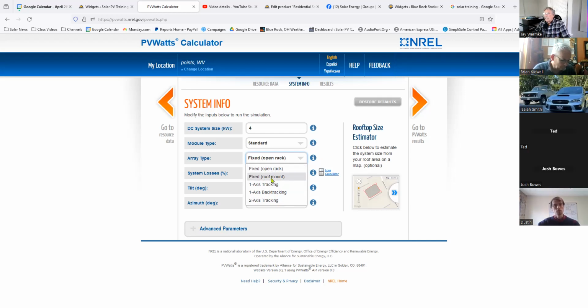So let's assume, just for this problem, I'm going to put it on your roof. So I picked roof mounted, and then we measure the angle of your roof, and we find that it's 17 degrees. And we also find that the azimuth of this particular building we're putting it on is 145 degrees. It's not perfectly due south. It's 35 degrees off south. Now, I'm just making these numbers up, but you would do this during the site evaluation.